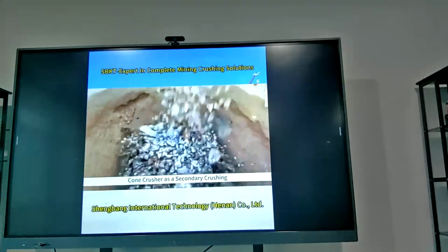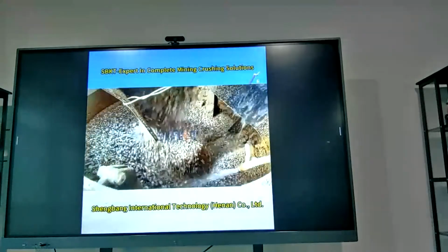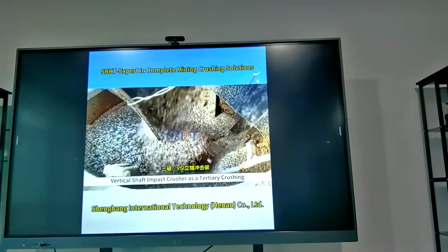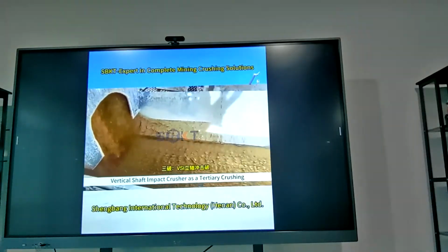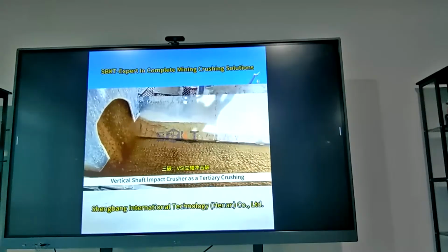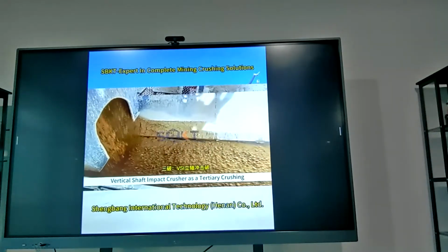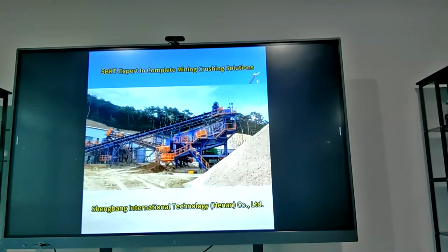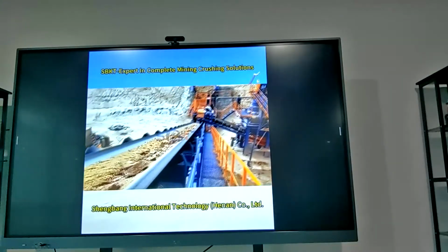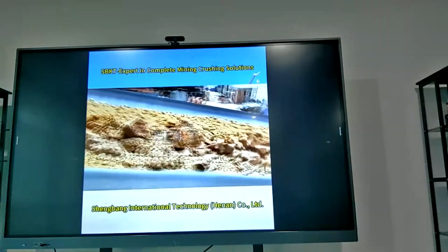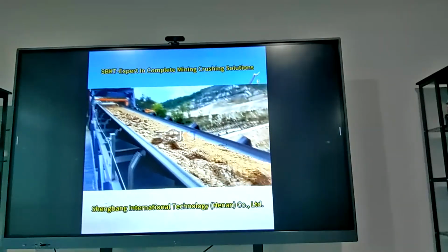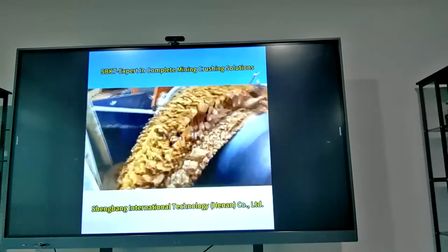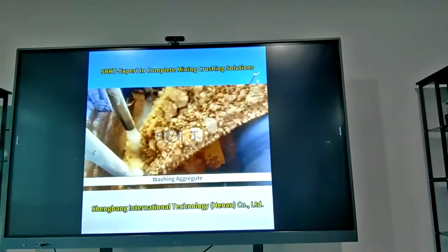Next, we focus on the parts of the feed and crushing chamber. The ordinary jaw crusher generally adopts a semi-V-shaped or oblique V-shaped crushing chamber. The width of the feed opening is relatively narrow. The ability to handle large-sized raw materials is limited. The flow path of the material in the crushing chamber is not optimized, and it is easy to cause blockage, affecting the crushing efficiency.